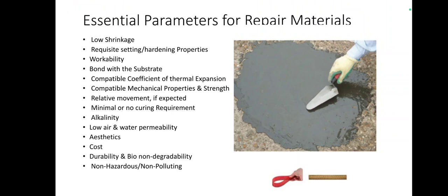It should also try to move along with the existing material, and it should have minimum or no curing. As I told, repair work is done in case of emergency maintenance, or in case of repair of a concrete road, so it should be immediately allowed for traffic. We can't wait for 7 days or 10 days to do the curing work.